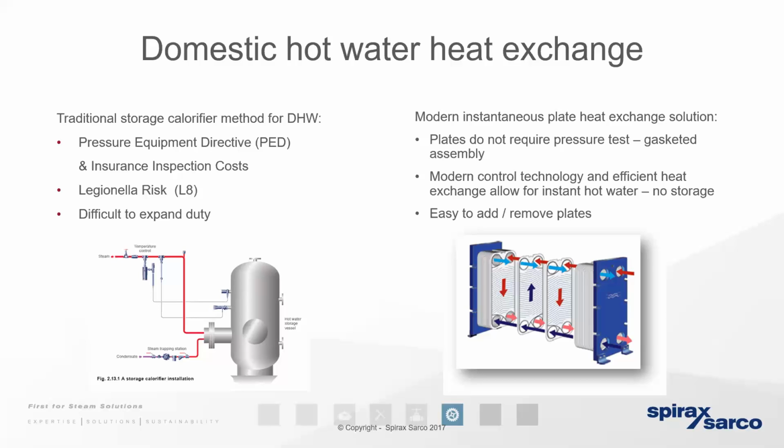But it also means we're going to have a fixed vessel. It means not only is that storage vessel a fixed size, but the tube bundle assembly is also going to be a fixed size. That A value that we spoke about is going to be fixed. And it bears mentioning that a tube bundle assembly, if we laid it out on the floor, it'll take up a significant footprint of space. And that's one of the reasons why storage heat exchangers will take up a significant space in the plant room.